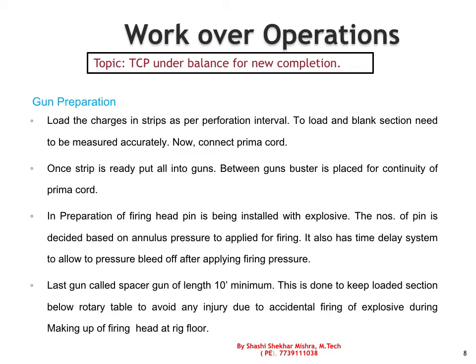Then we prepare the firing head. In that preparation of the firing head, we put explosive, and the shear pin is also installed in that, and that pin rating is decided on the basis of the pressure that we are going to apply for this firing.